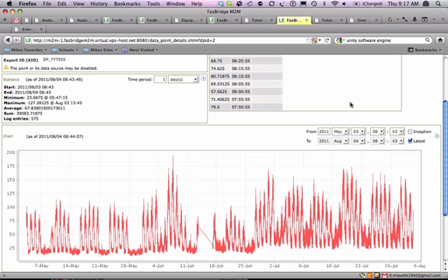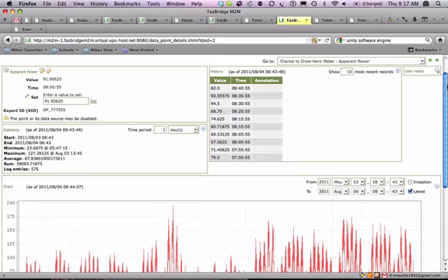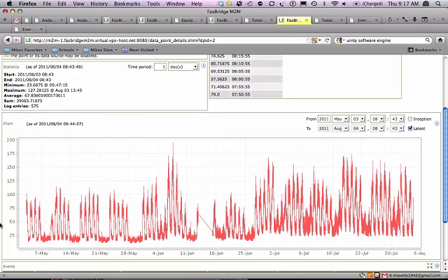For something like A Chance to Grow, or any of the buildings for that matter, it's also interesting that you can look at the entire period of time and recognize what's been going on with the power in the building. We had a very high spike on this particular day, much higher than it should have been. That's the kind of spike you can get charged significantly extra for if you don't have some management control, some method of flattening it out.